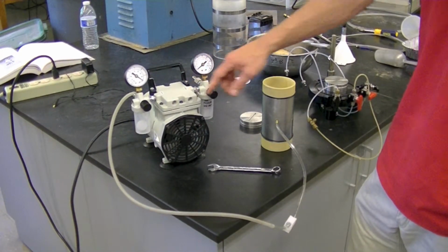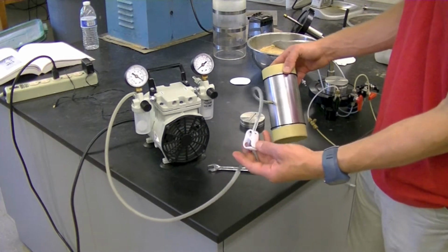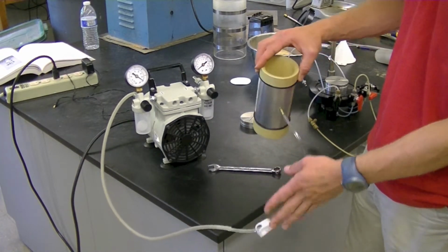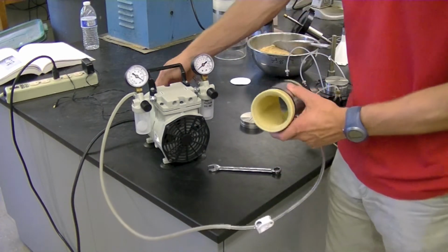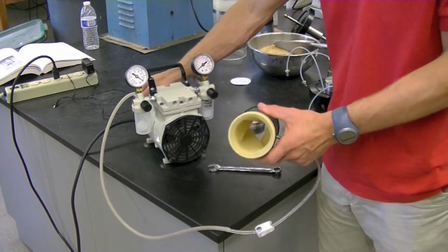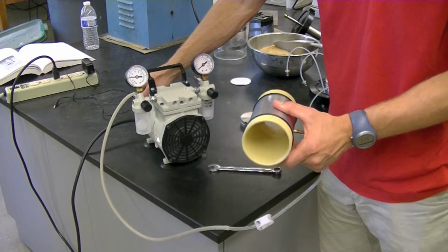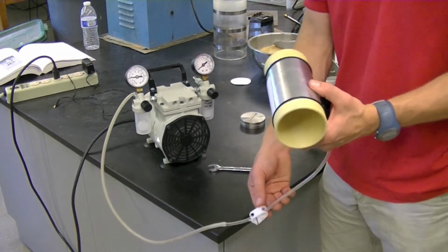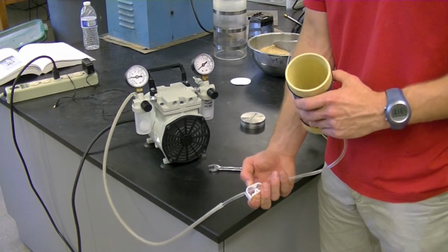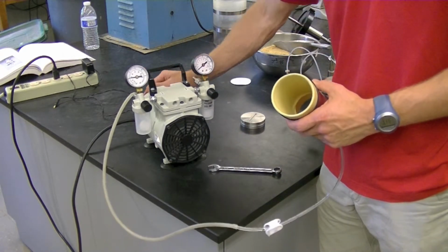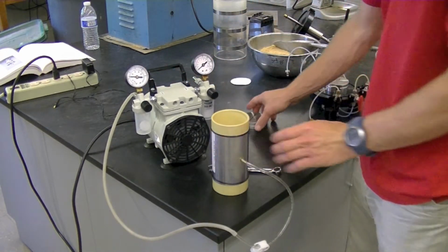A triaxial mold with a tube stem is needed. A bladder cylinder or rubber membrane fits inside the mold, holding the specimen in once the mold is removed. A vacuum must attach to the tube stem to remove air from the outer diameter of the rubber membrane and the inner diameter of the mold. A plastic pinch is attached to the tube stem to close off the vacuum when necessary.